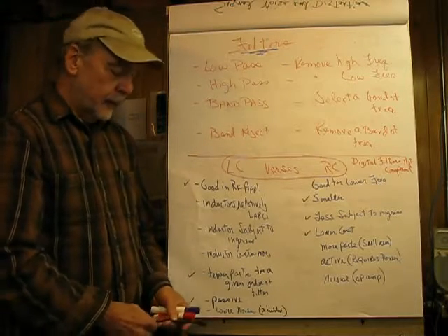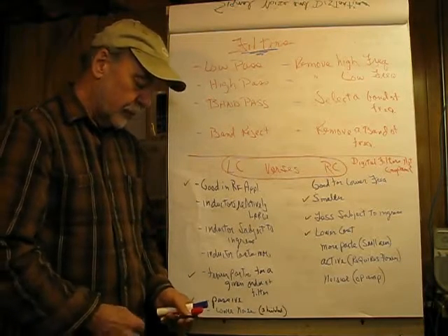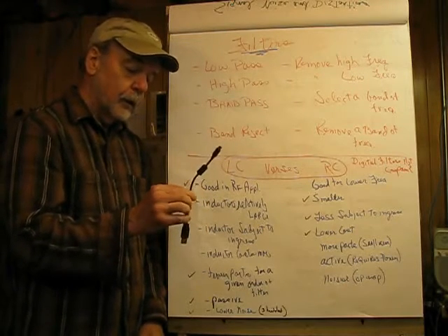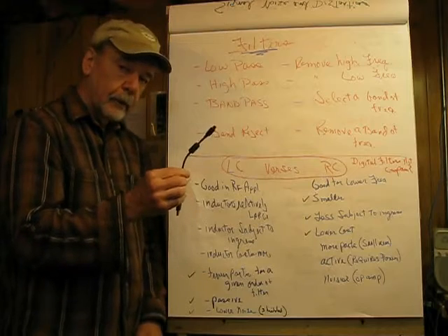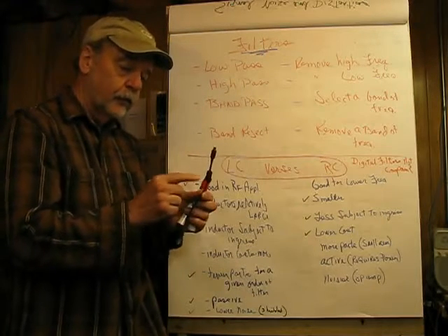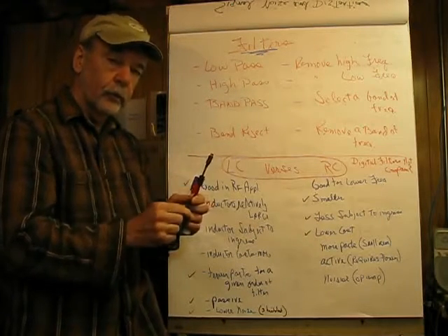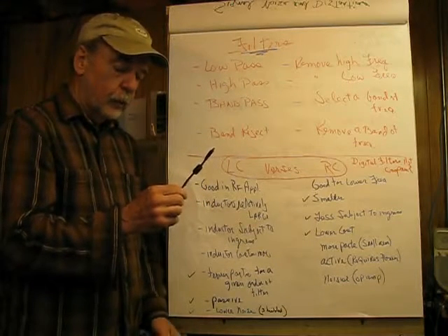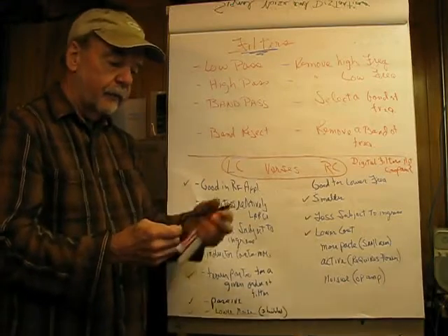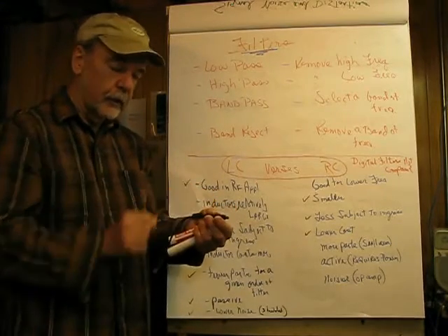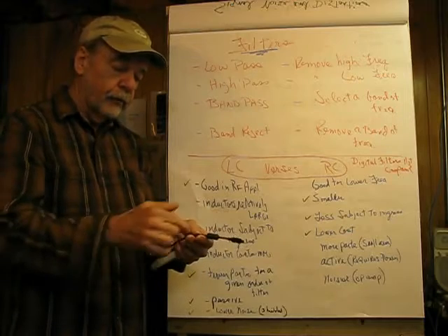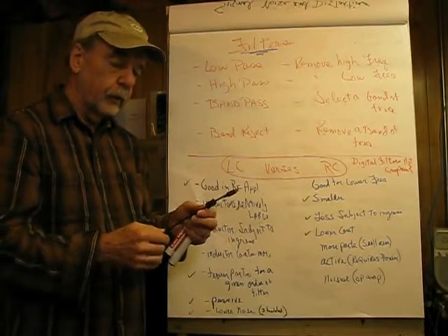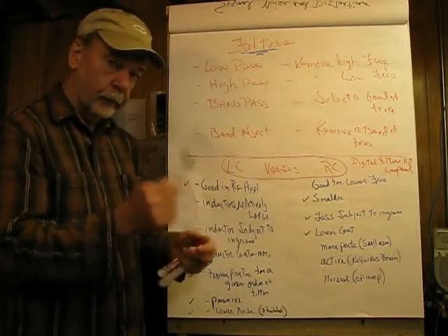Now when we look at low-pass filters, it doesn't have to be anything special. What I'm holding here is a USB type A to mini cable, and we see this little lump in the cable here. You see these a lot on computer cords and monitors and so forth, and this is a low-pass filter. Its purpose is to keep any high frequencies from the device that we plugged in here, say an MP3 player, from using the rest of the cord as an antenna. So anytime you see a lump in a wire, so to speak, it's a low-pass filter.